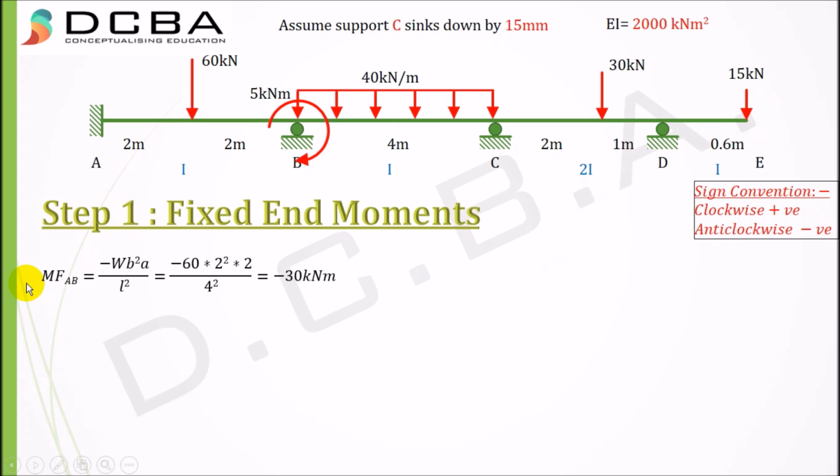So the fixed end moment MFAB will be minus W B square A by L square. This is the fixed end moment for a point load acting at a distance of A. Though it is acting at center, I've still used this particular formula, and it is minus 60 into 2 square into 2 by 4 square, equal to minus 30 kilonewton meter, minus because at this end, that is AB, there will be an anti-clockwise fixed end moment.